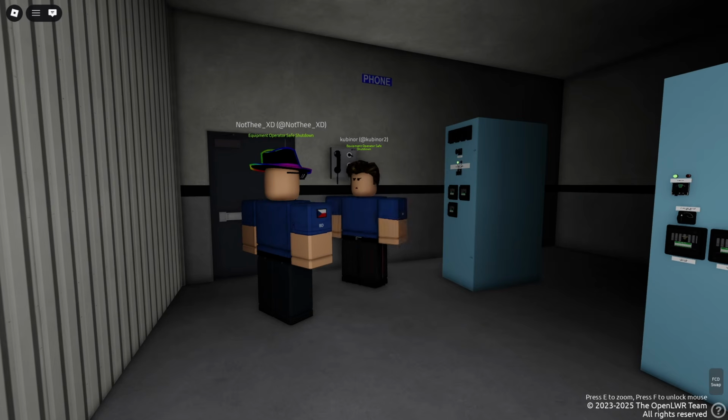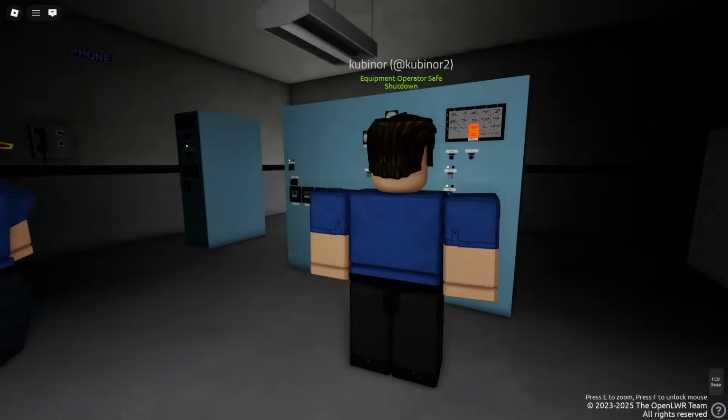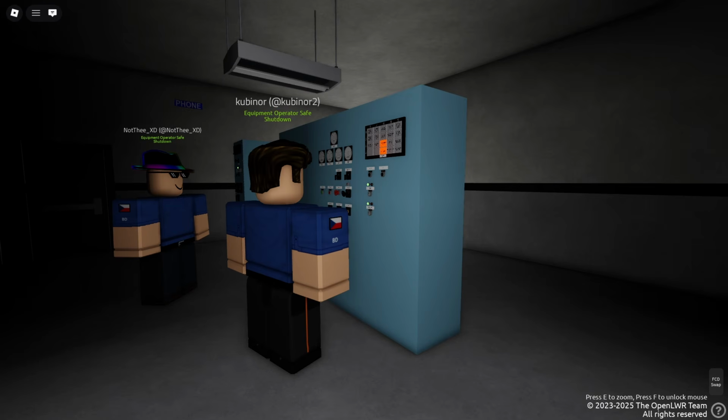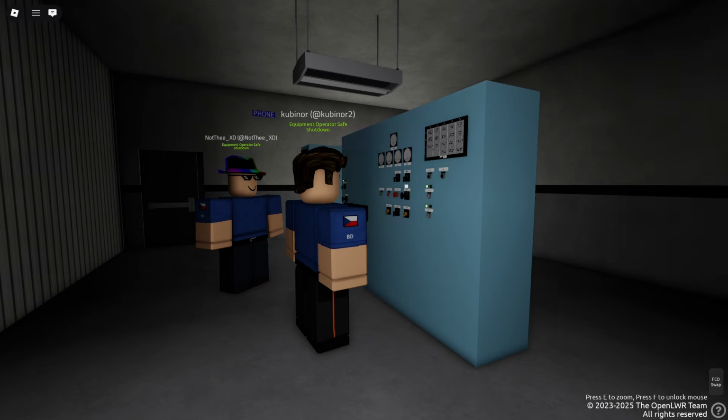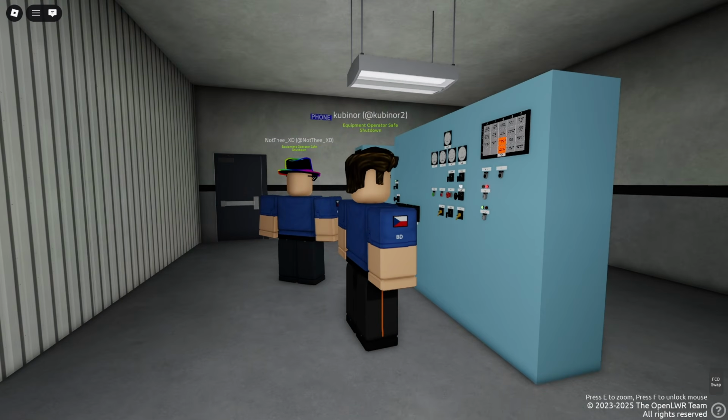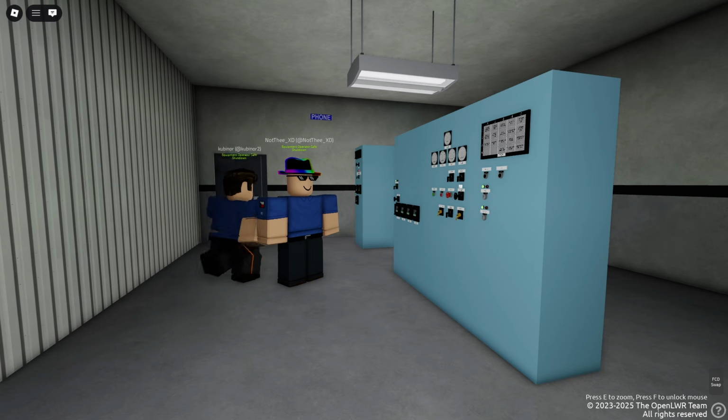Okay, so we will be restarting the DG2. I will be resetting the unit lockout relay, DG relay 86 DG2. You'll be resetting the DG lockout relay. That's correct. We have an excitation run up. And we have a successful DG start.